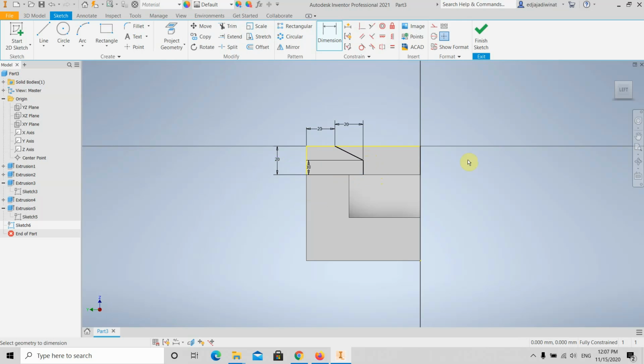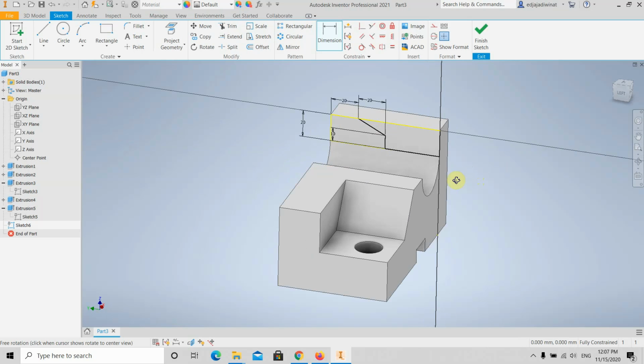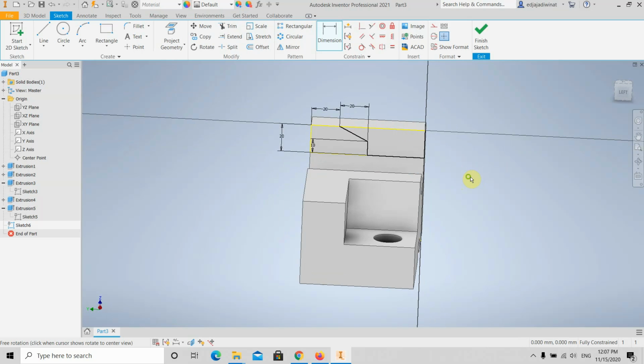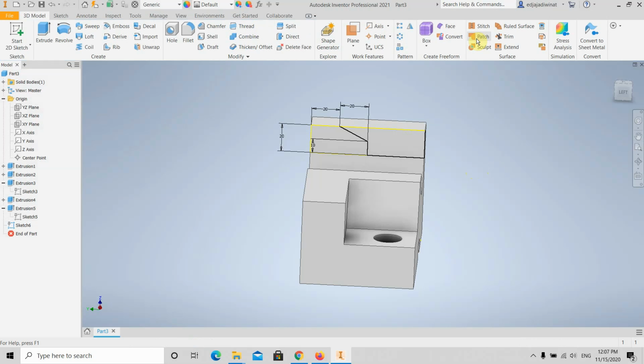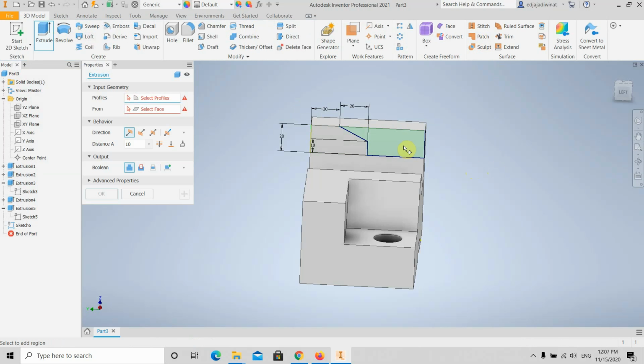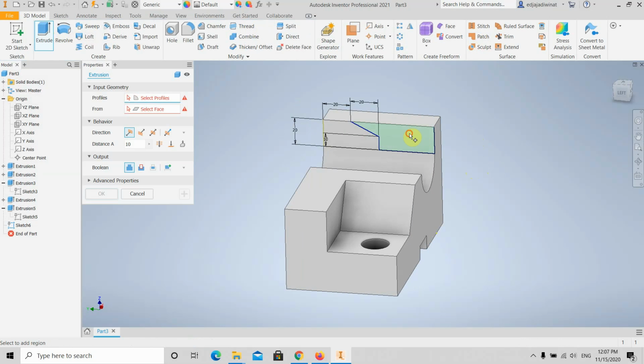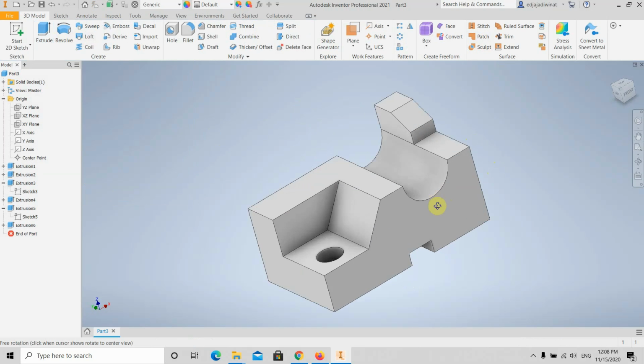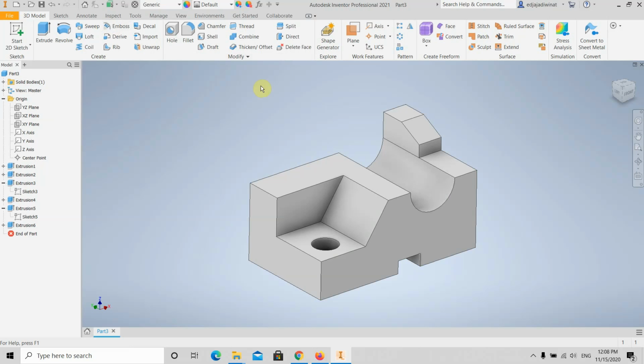So we are done in making the sketch. It's a fully constrained sketch already. So 20, 20, 10, 20. Okay, looks good. Finish your sketch and then extrude. Select the sketch. Then you cut to the back. Just flip through all, press OK. So this is the object that you have drawn. Press save.